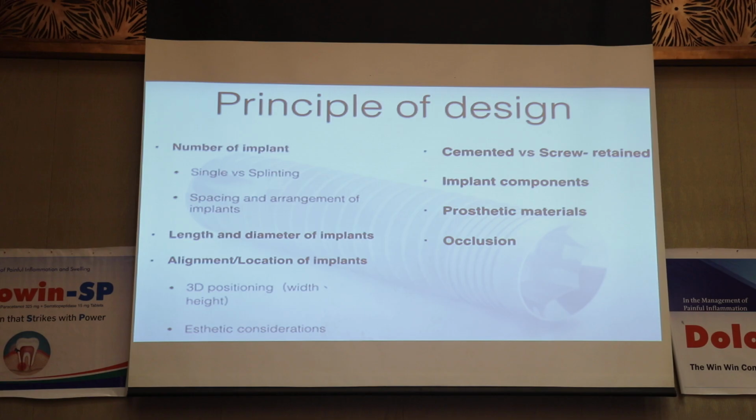But in most cases it should be a screw, whether it's a titanium screw. Sometimes what will happen is it will get cold welded inside the implant inner structures. So that is one of the failures. So always you have to give a passive fit of screws.